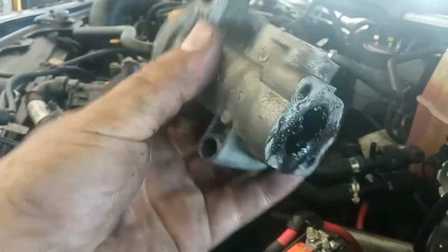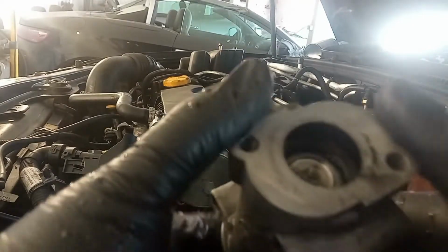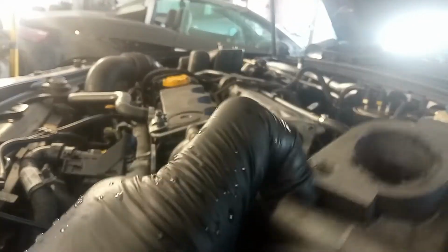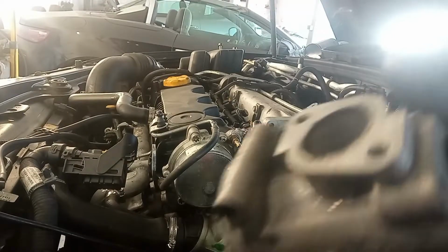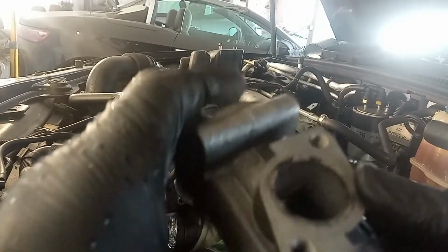Just try to clean that out and try to reuse it. All cleaned out. Works like a charm. In fact, I never had to replace an EGR valve body. I just clean them very well, and if the electrical part is working, I just reuse them.